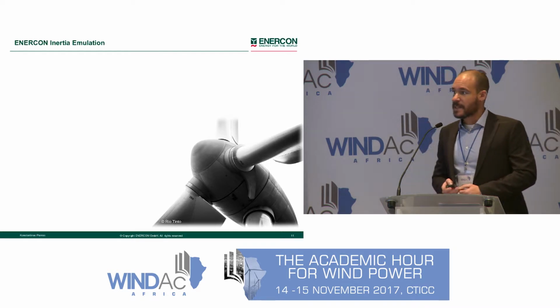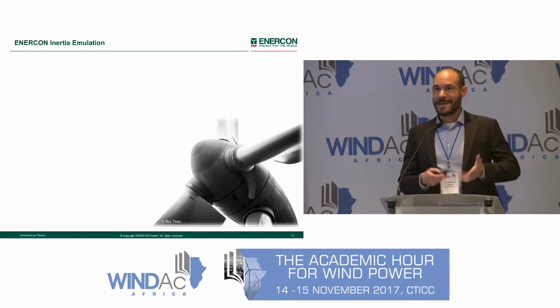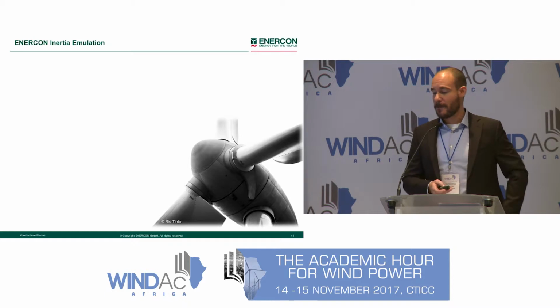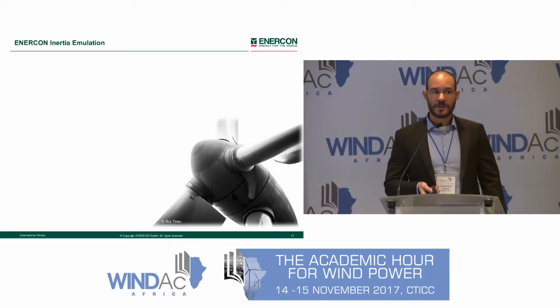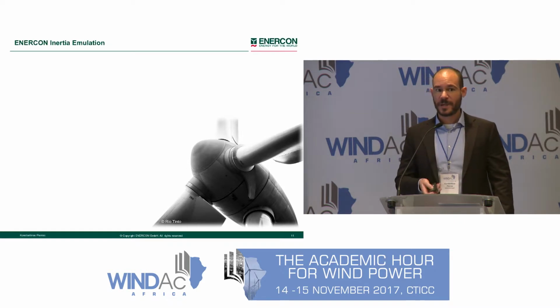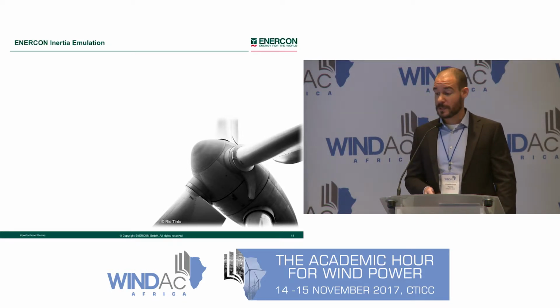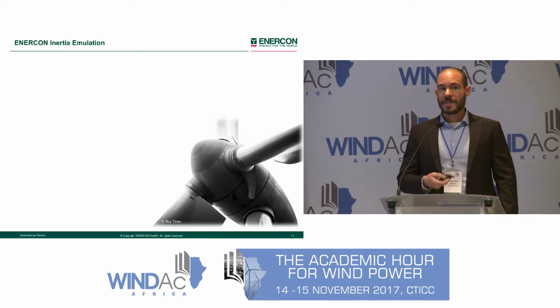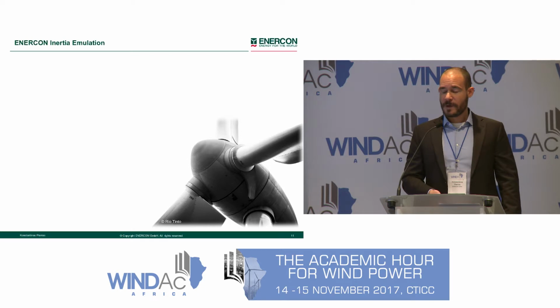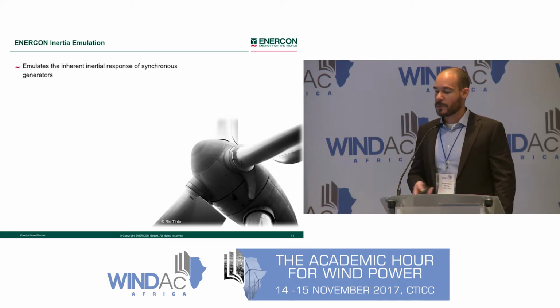In response to the synthetic inertial response requirements introduced by Hydro-Québec, Enercon was one of the very first wind turbine manufacturers to develop and present the inertial emulation feature, already in 2009. The inertial emulation controls are implemented at the wind turbine generator level, and with it, wind turbines can emulate the inherent inertial response of synchronous generators.